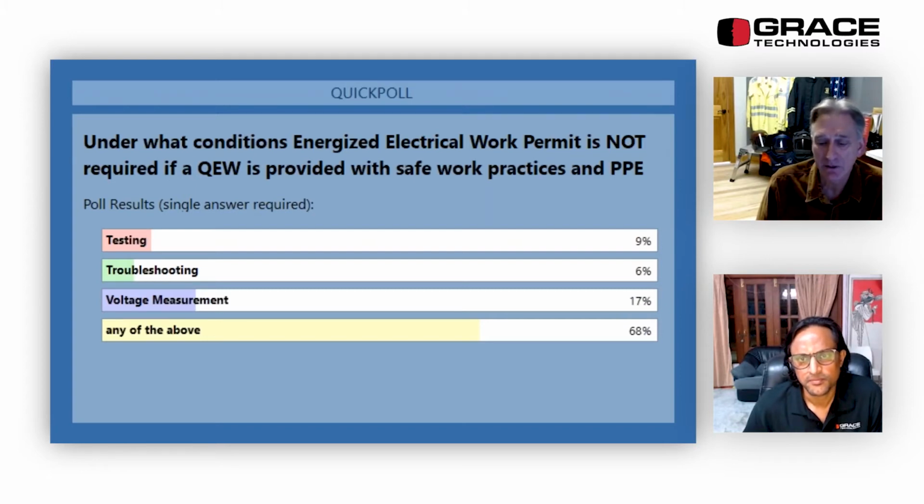I know that I do a risk assessment. Some companies have done that, and they may determine that, all right, if it is finger safe or touch safe, then it would be okay to replace a fuse once the disconnect switch is opened up. But I would think a lot of companies would say, no, even if it's finger safe or touch safe, we want it shut off upstream from that.